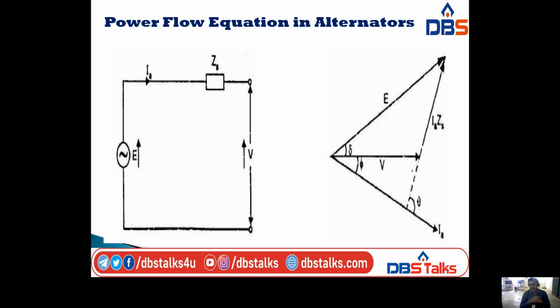Next, we have the phasor diagram of this concept. Here I am taking the voltage V as the phasor reference line, indicated as a horizontal line. Next I draw IA, which is lagging by angle phi.